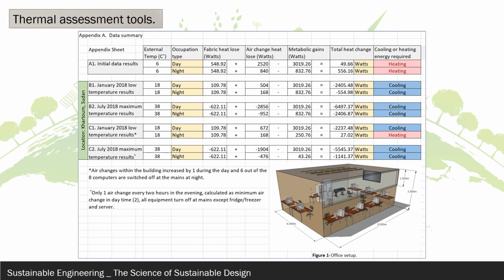The first slide of the table shows you the different temperature changes between the external and internal fabric. We then looked at the energy losses through that building fabric against those temperatures. We're then using an assessment of the air changes and how much energy would be lost against Tipsy guides. You can see how many air changes you would need to reduce the temperature to understand the energy losses within the building. Then looking at the metabolic gains, which we talked about earlier, of people, equipment, kettles, sunlight and natural light, and how these can affect the inside workings of the building.